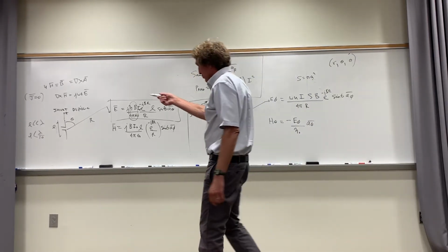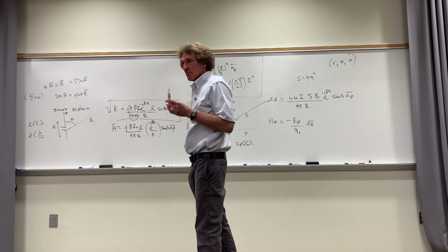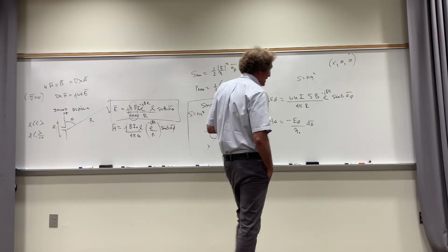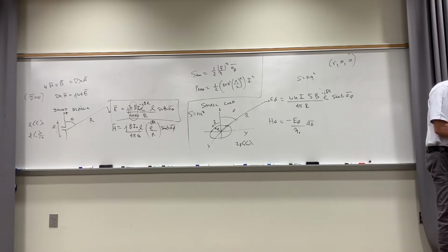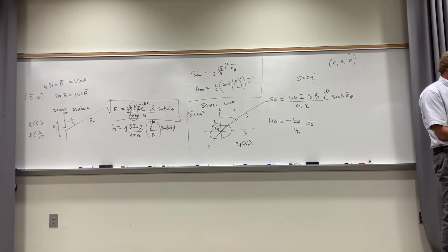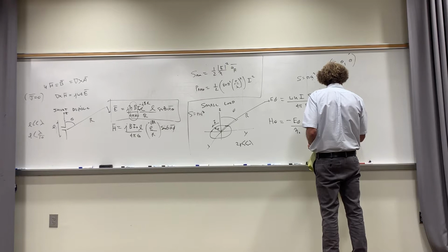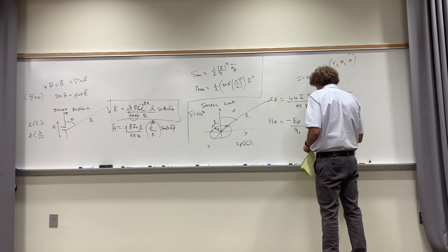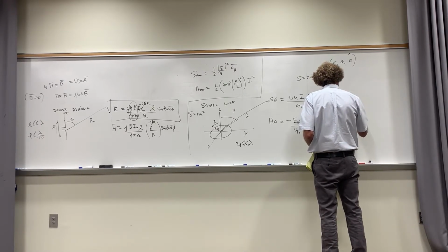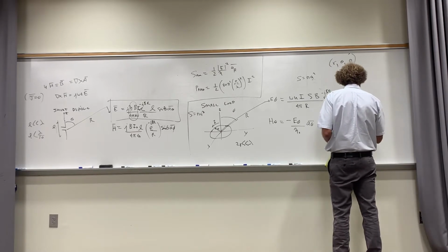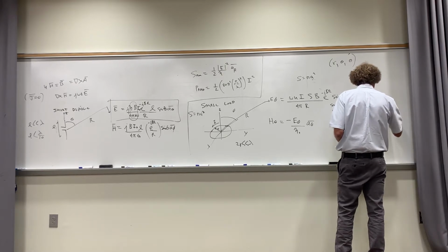As the wavelength approaches the length, the radiation pattern changes markedly. Remember that. It's all about what things are relative to the wavelength, the length of the antenna. Now the radiation resistance, he puts it down in his book, but just put this down: the radiation resistance for a small loop is equal to 320 pi to the fourth, and then it's S over lambda squared ohms.